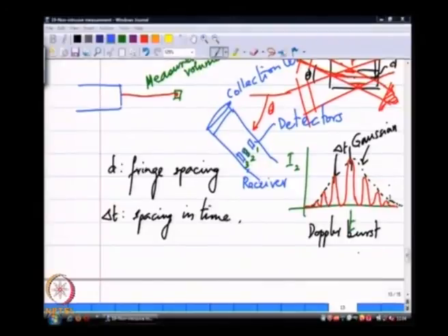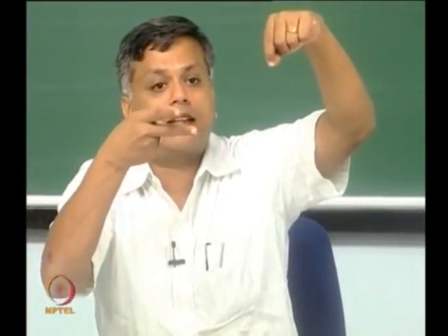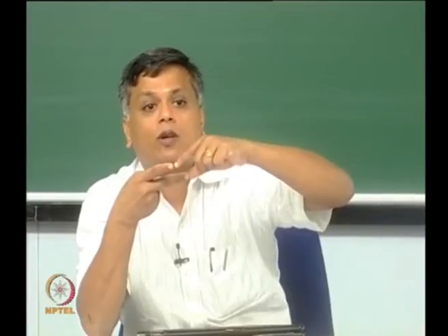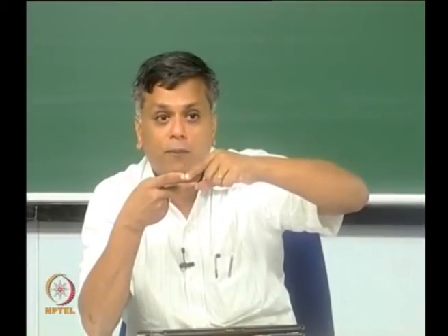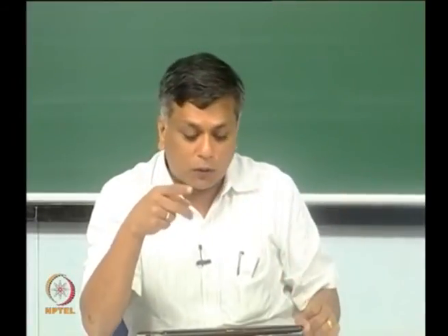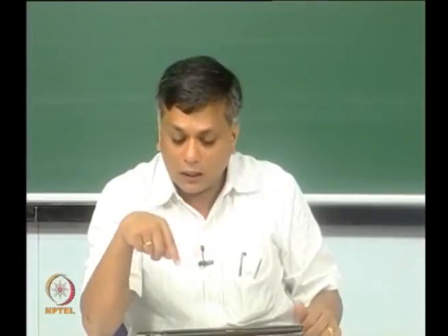So, in other words, when a particle passes through the probe volume, detector 1, which is spatially separated from detector 2 inside the receiving optics, sees the Doppler burst at a slightly different phase. The 2 detectors see this at a slightly different phase. From the phase difference between I1 and I2, as well as the peak in the frequency from any one of the 2 detectors, we can get both the fringe spacing related to the size and the droplet velocity related to the peak frequency.